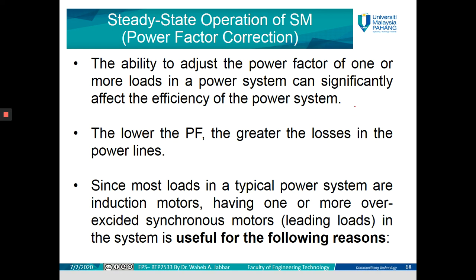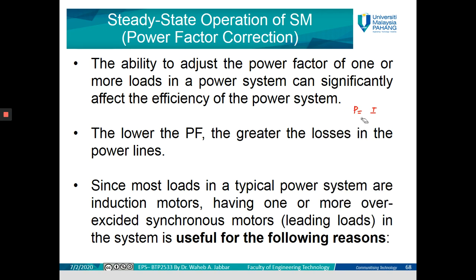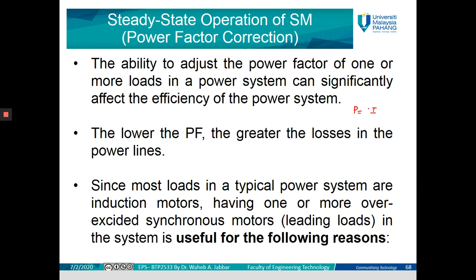Because the power is equal to V times I times cosine theta, the value of the power factor will affect the real power, and also the reactive power of the system. So the lower the power factor, the greater the losses in our power lines.